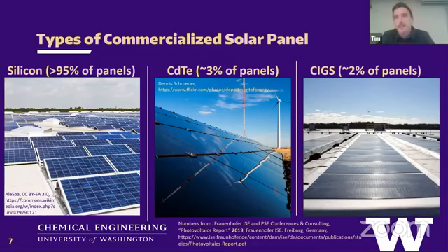Yeah, it has to do with climate, average temperature. With silicon, for any technology, your efficiency is not constant as a function of temperature. So as you go hotter and colder, your efficiency will change. With silicon, the colder you are, the more efficient your solar cell is. And with cadmium telluride, the hotter you are, the more efficient your solar cell is.